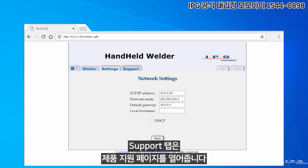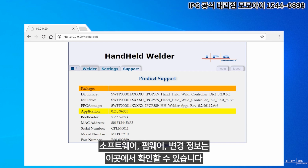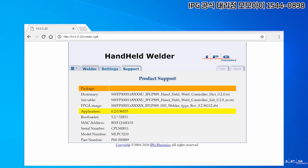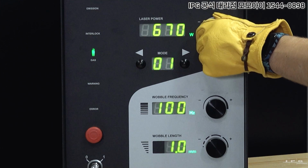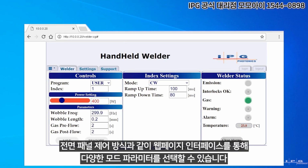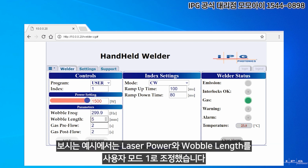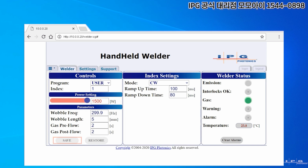The Support tab opens the product support page. Software and firmware revision information is located here. Now let's go into more detail on how you can customize modes for the LightWELD 1500. Just like using the front panel controls, the web page interface enables you to make changes to different mode parameters. In this example, we have adjusted the laser power and wobble length for user mode 1. After entering your changes, be sure to save your changes using the Save button.